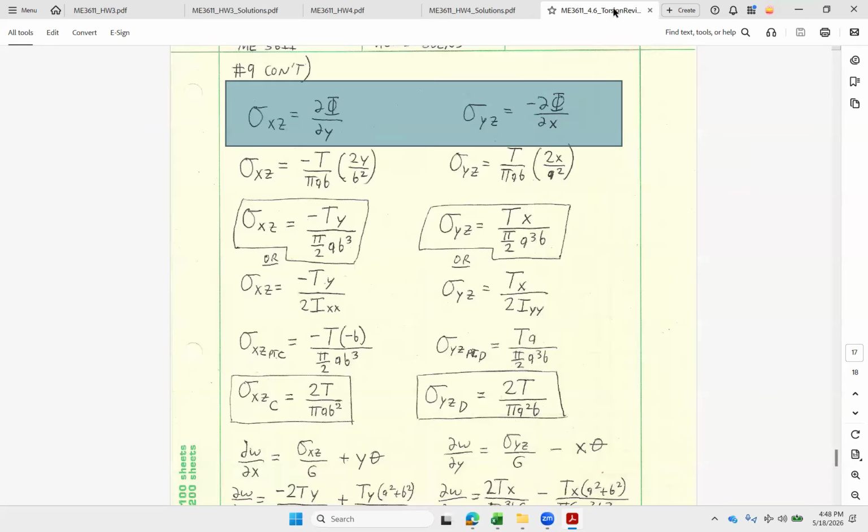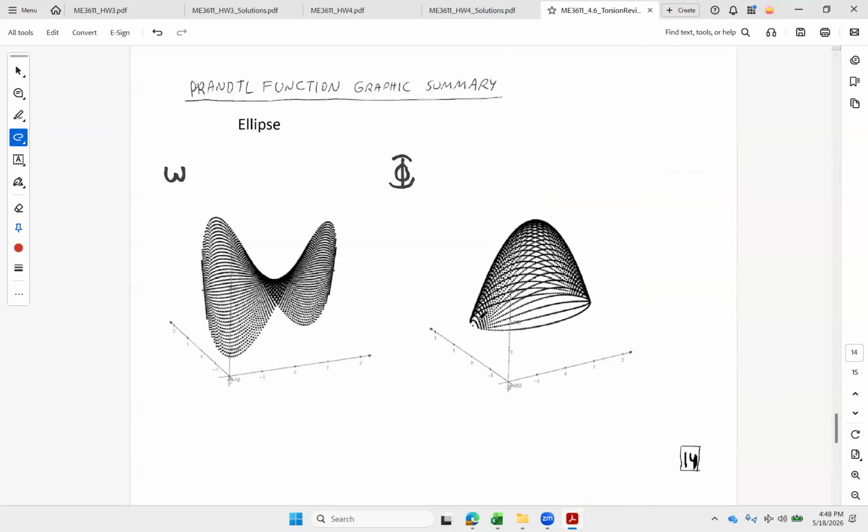So if we look on the ellipse, remember, I've got the same height, so I'm getting there from wider apart places horizontally. So here I've got a kind of steep slope and a kind of steep slope here. And these are fairly steep slopes in x, which results in my y stresses. Minus d phi dx gives me my tau yz stresses, and we can see it's pretty steep.